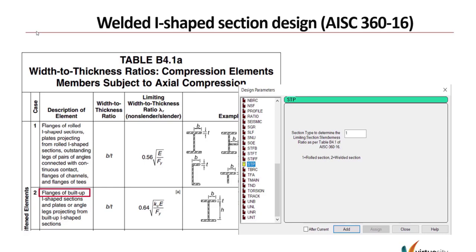Now see for example here, first of all, while we do the section classification, this is for AISC 360. When we do the section classification, which is a very important procedure for calculating the design strength of any member, the section classification is nothing but it is based on some geometrical shape of the section and also some manufacturing criteria, like whether it's built-up or whether it's hot rolled.